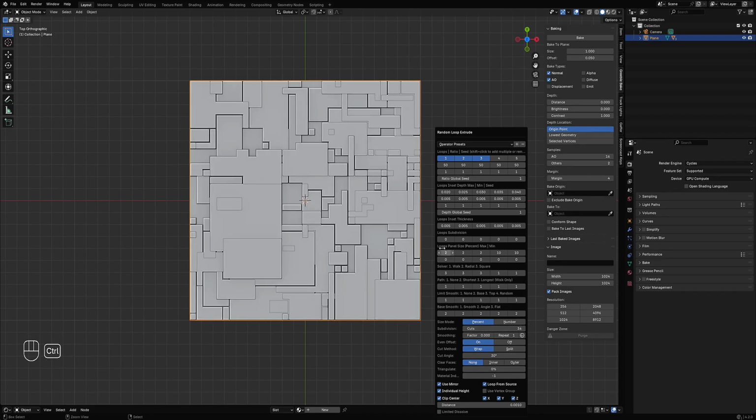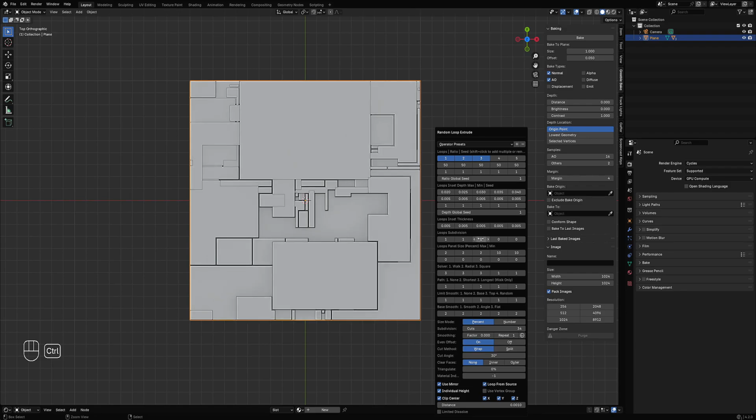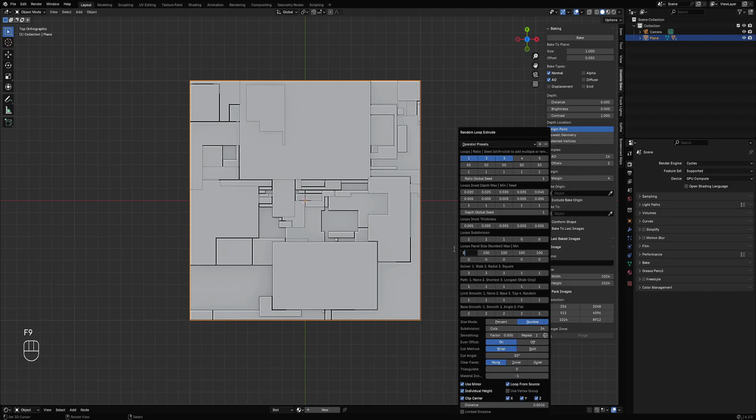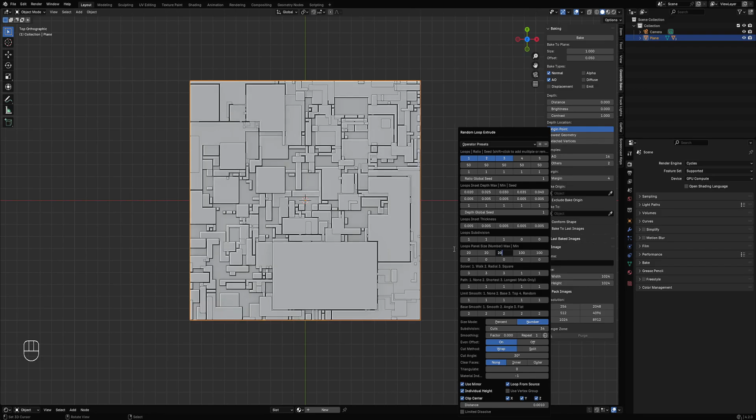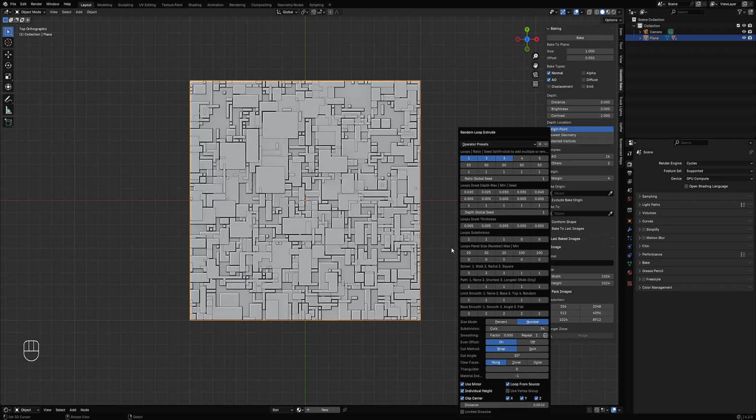So we're just going to let's try number and use something like 20 faces for the maximum of the face islands. Okay. I want to make the inset depth lighter. So 0.01, 0.015, 0.02. And also the inset thickness. So 0.003.